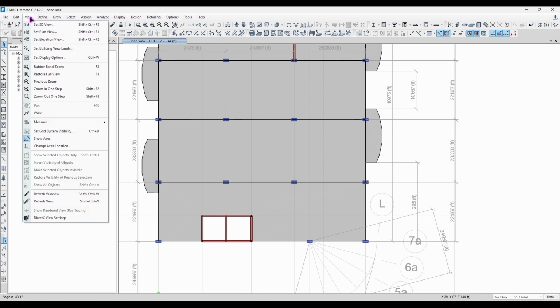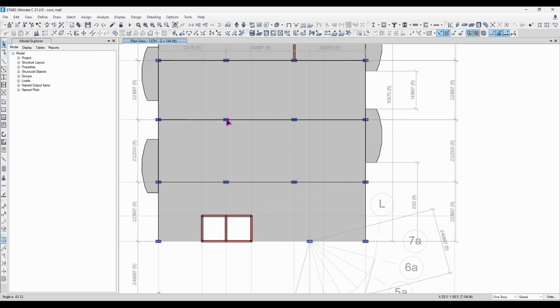And if we go to View, last but not least from the measure is the area. Now you just want to measure the included area between these four columns. If you can't really snap it back to close it, you can just right click anywhere and it's going to just continue the shape. Now it tells you that the area is approximately 581.4 feet squared, and the perimeter is 96.5 feet. So it gives you both the area and the perimeter.